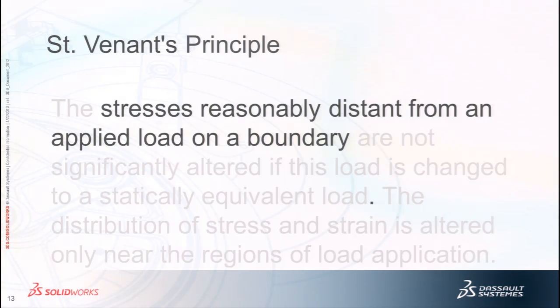If you're adding details inside, how badly is it going to affect the physics? For one example, you could have it bonded. I don't know how many of you are familiar with bonded, but you just take two faces and say they are always glued together. That's very fast, it runs quickly. Then you come to the submodel, and maybe you want to actually fasten these two plates with bolt connectors. So you're not changing the physics too much here, but you're adding a little more detail. You can't just come to the submodel and leave it free so that it starts moving out. That assumption won't work. So you have to make that judgment when you do that.